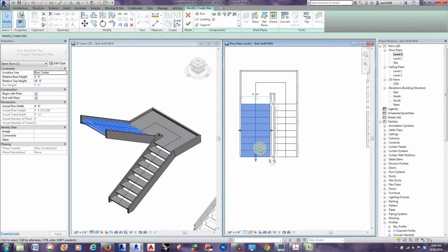But for instance, for egress codes, where you have a fire stair and a certain occupancy load, when you look it up in the codes, you'll take that load and apply a multiplier. I think it's like 0.02 per occupant, and that tells you how wide your stairs or how wide your doorways need to be for fire egress.